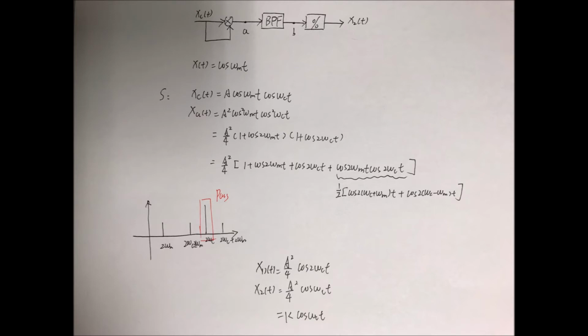Because my carrier frequency is embedded in the signal, we can extract it. And this method is also used in many other areas, for example digital communication systems. You have to know the clock, you have to know how long a bit is. So finding the clock is very important.